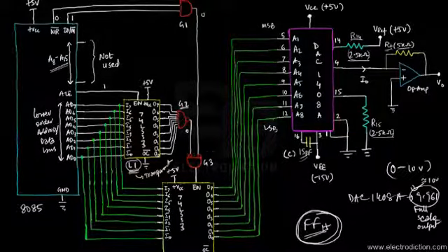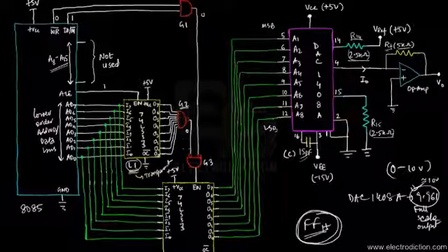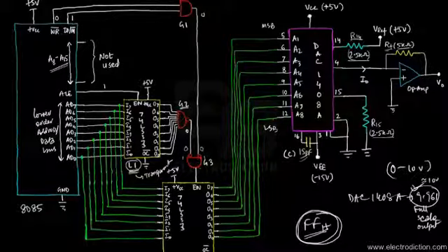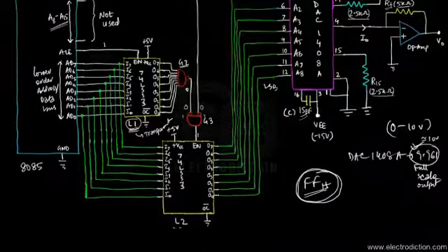So whenever we have zeros over here, they get converted to 1, so it just gets complemented, and those ones are sent by this AND gate G3. Now you can basically understand that whenever two zeros fall in, both zeros get converted to ones by the input of the gate G3, and whenever these two ones are ANDed, we get a logic 1 at the enable input of the latch chip L2.